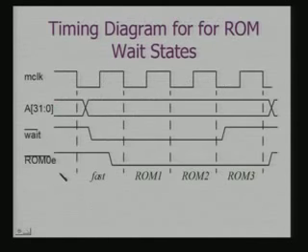But now, let us look at this timing diagram. Effectively, what we are telling is, this wait goes low here, and this ROM enable has to be active for this time period, because these are the 4 cycles which are required for the access. So, this is now the timing diagram that would be there when I am using a ROM which requires 4 clock cycles for an access.